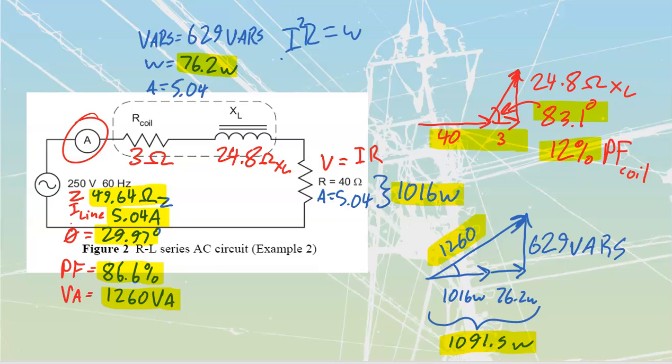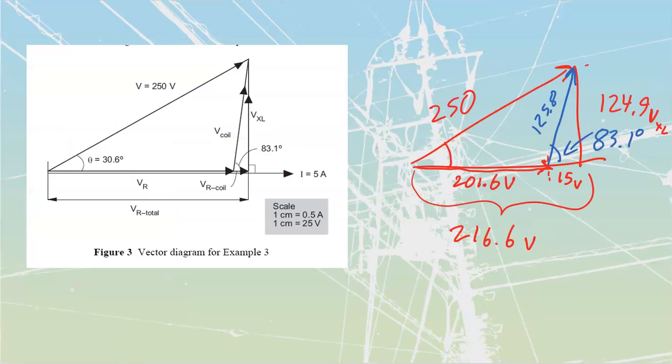If I go back to this circuit over here, if I were to throw a voltmeter across this inductor, when it's operating, I would be measuring that value of volts. V is equal to 125 volts that I would have all the way across from one end to the other, because I cannot separate out the resistive and the inductive sections. They're just intertwined. It's going to be impossible. What's kind of cool over here as well is that we solved through it like this by taking these ones here and adding them together. There is an alternative method.